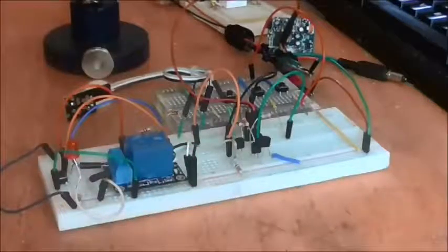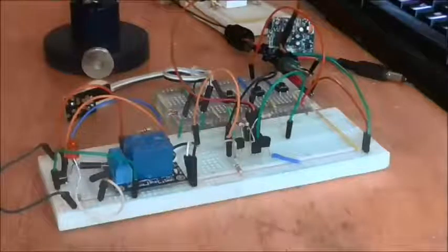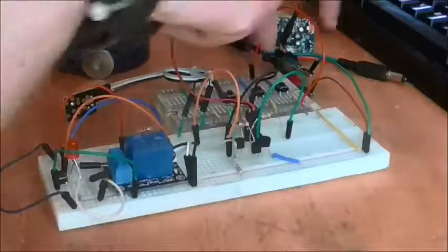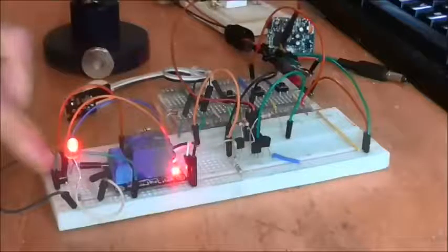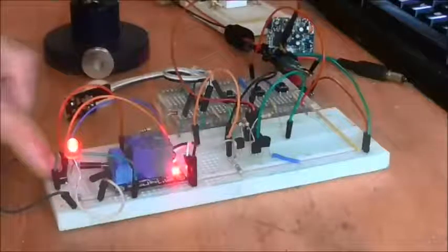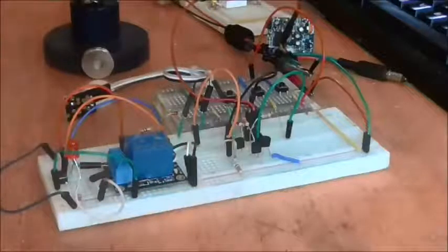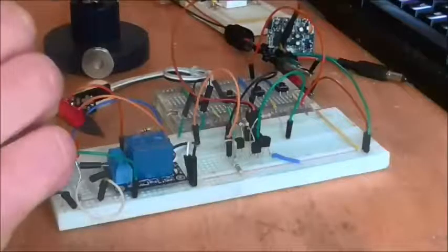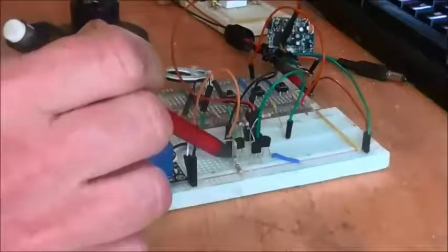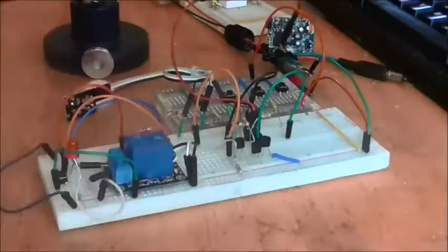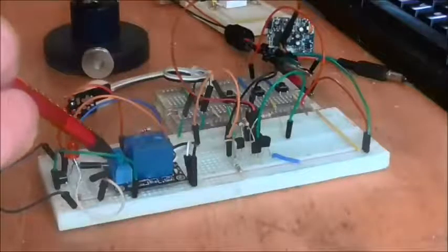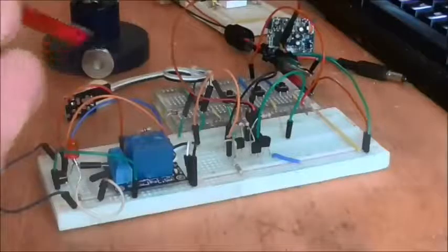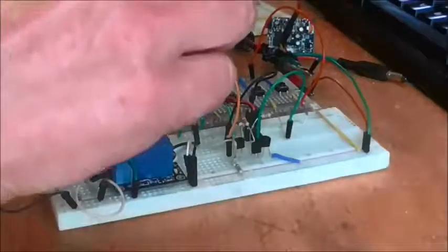Now normally a reset switch would be a key or perhaps a concealed button, and here it's just a normal push button. Now what happens here is that as the relay switches on, which it does by the output of the gate there, the normally closed switch will shut out and the normally open switch will become active. Through this blue wire, current goes up here and then it's shared.